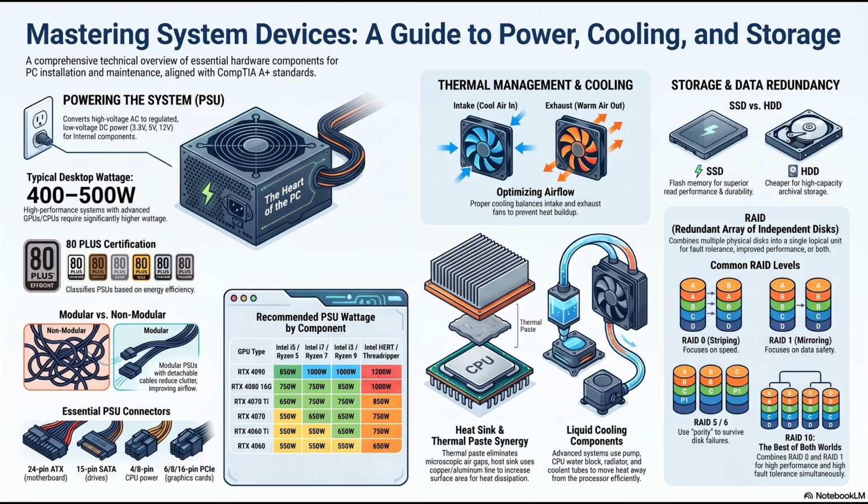Oh, really? Yeah, because the power supply is bracing itself for a massive influx of 230 volts, but it only receives half of that. The components essentially starve. The system simply won't turn on, and you might spend an hour troubleshooting a black screen before realizing your mistake. So it's totally harmless. It is harmless. That's a relief. Let's reverse it.